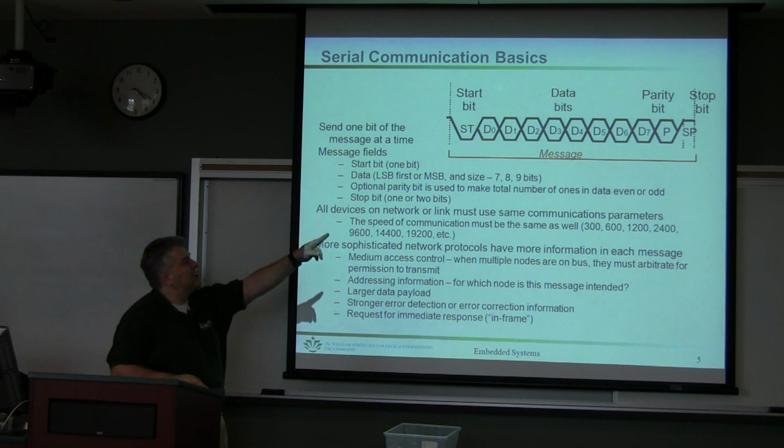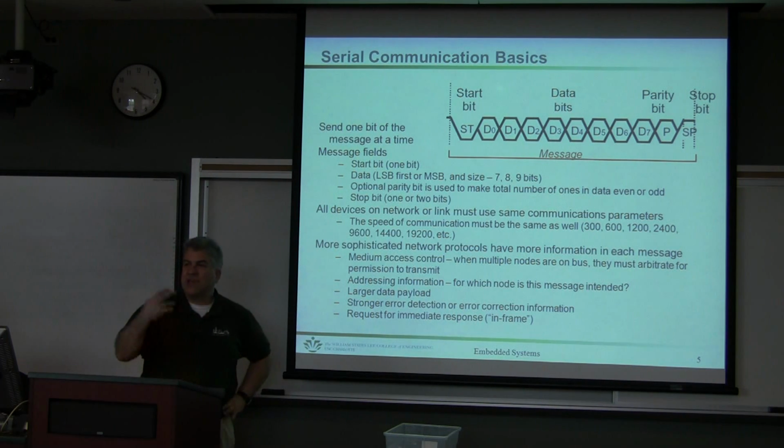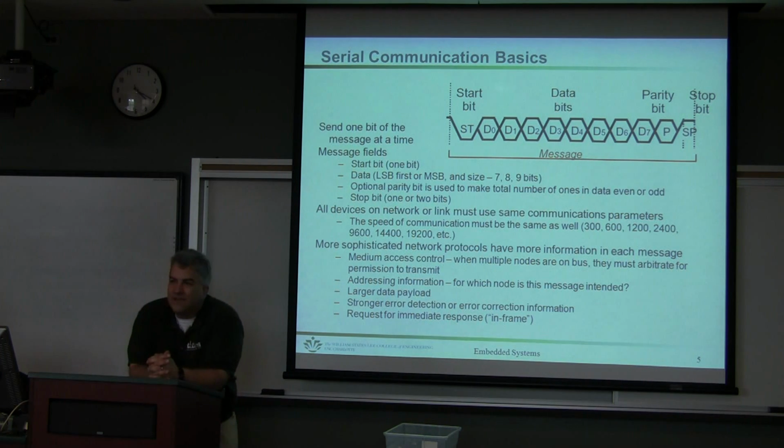Now, with each data bit it sends, why can't it just do that all the time? Think about it: when it's sending each data bit, it's either a 0 or a 1, so you're never assured of having an edge to be able to synchronize it.